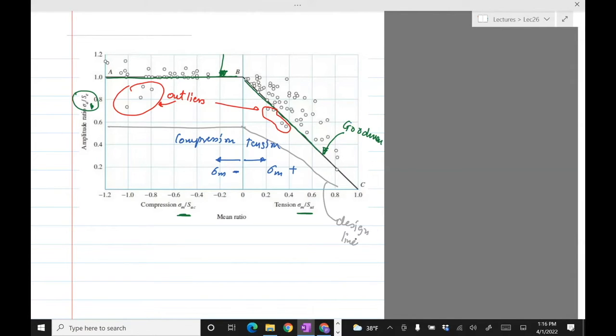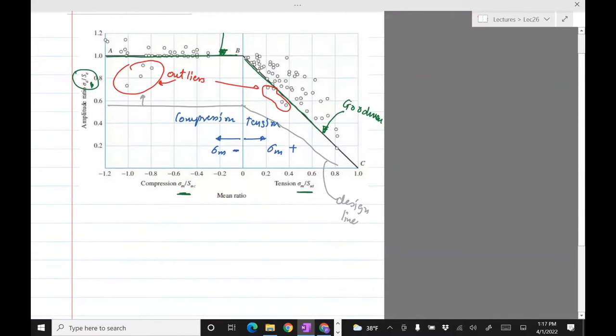But when you have the design factor, you'll see that your material will become bigger, larger, have more mass, and that would waste material and so on. So you want to push that limit as much as possible so that you are up closer to that line, because that will make the design light. At the same time, avoid these spots so that you are not letting your material fail. So I've written down the equation for the right side, the Goodman line.